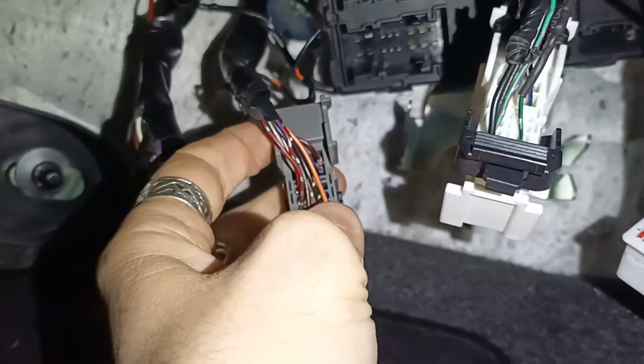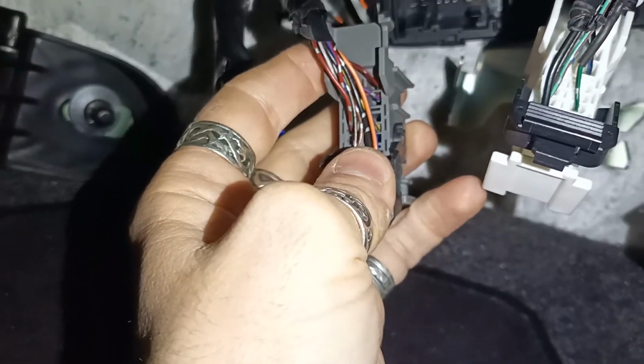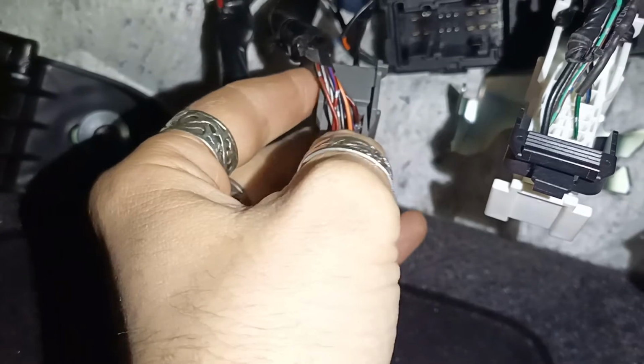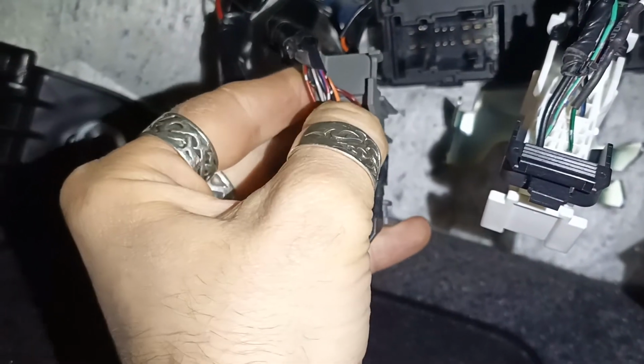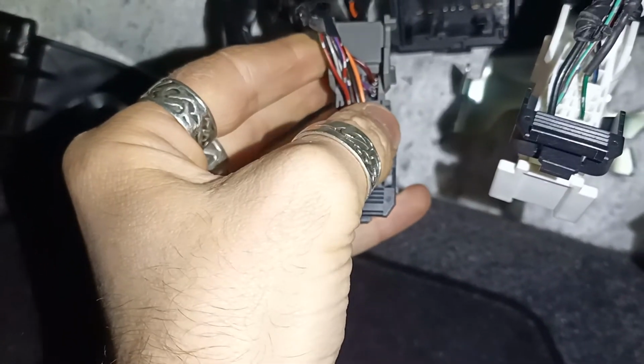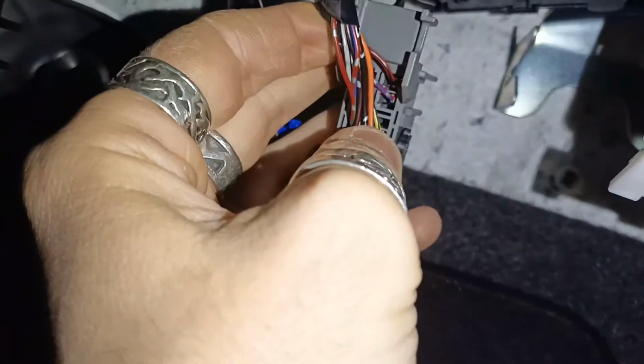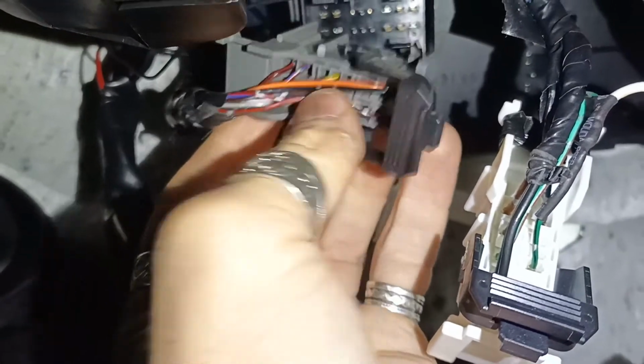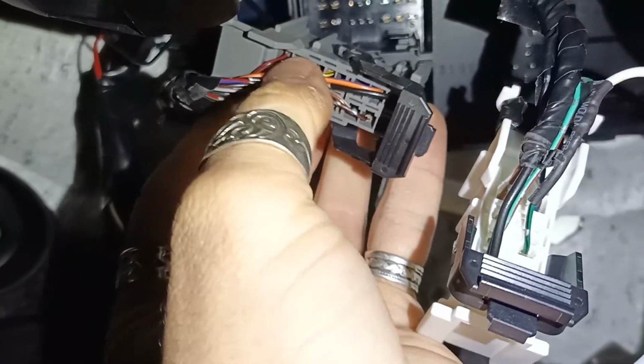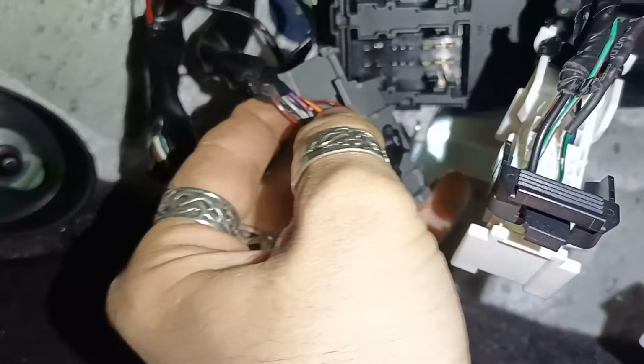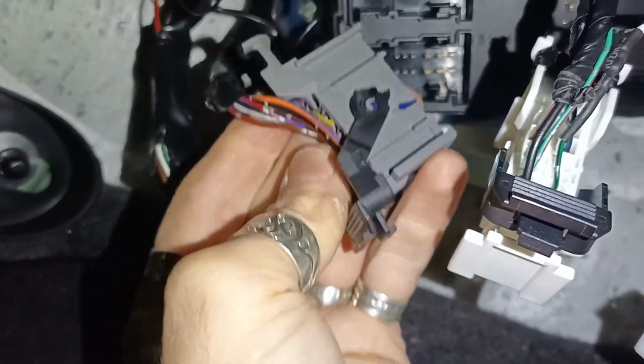And the last one is in this connector. This is the unlock signal, and the proper wire is this red with black at the top. So looking at it like that, it's the top right. When it's in place like that, it's the top again, but left. The red with black, that's the proper cable. Okay, so now let's do the documentation. Of course, let's turn off the torch.